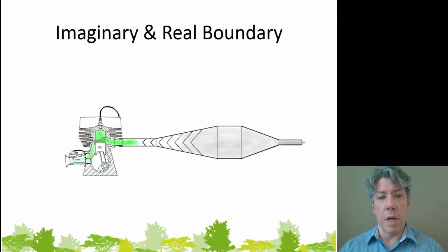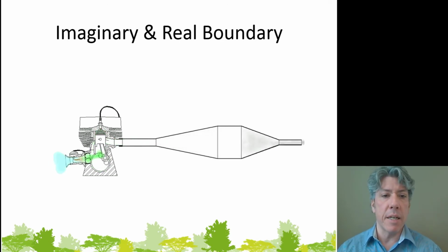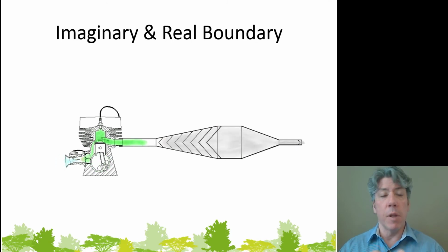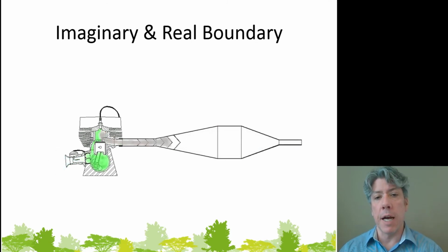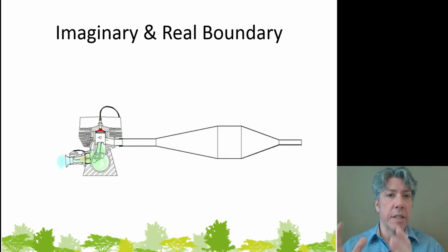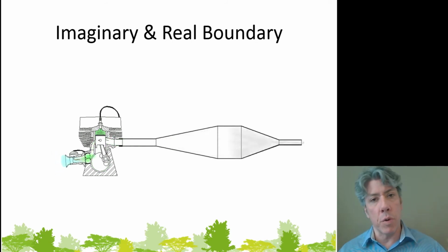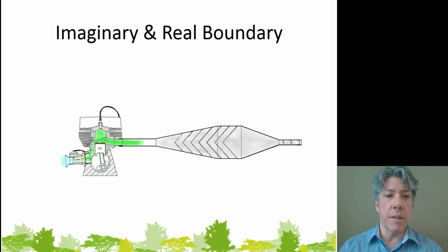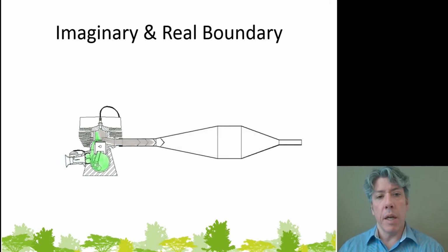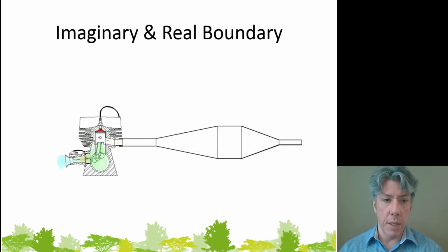So scavenging the exhaust gases is a very important thing. If you look at the assembly off to the right, the largest part of this animated diagram, you'll notice that the exhaust gases kind of bounce back into the combustion chamber. Well, that's intentional. That's by design. If you increase the flow area, what happens is the flow will slow down, right? It'll decrease velocity. And so what you've basically got there is a big mass that the next charge can bounce off of and come back into the cylinder to be reburned. And this can increase the efficiency of the two-cycle engine.